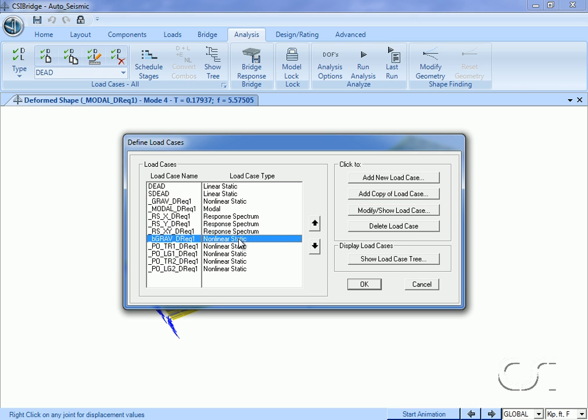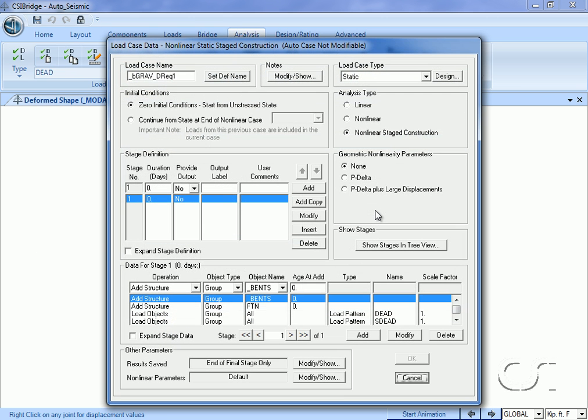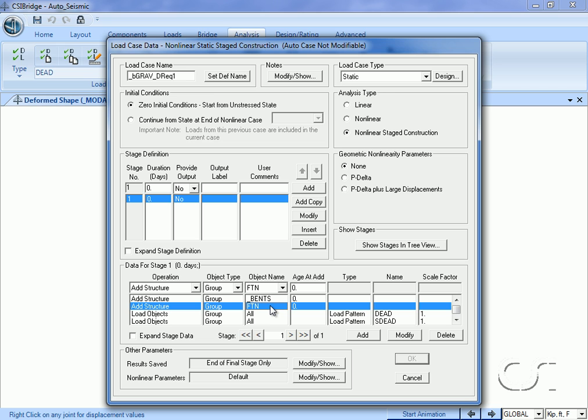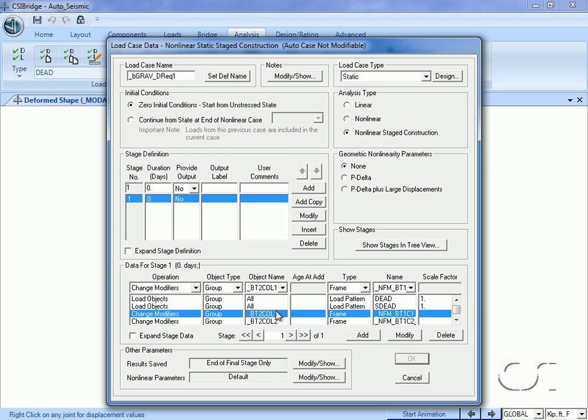The next case is associated with step 5 and again represents a dead load case, but this time consists of only the bents and foundation structure loaded with equivalent loads from the bridge deck. Again, cracked sections are used, and this step is needed because the structure is seismic design category D, which means a pushover of the bents is required.